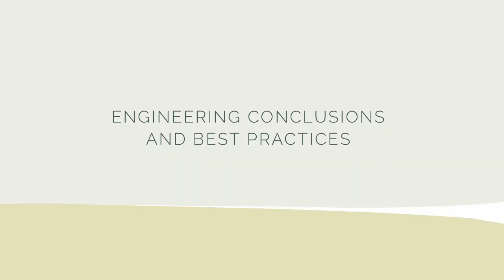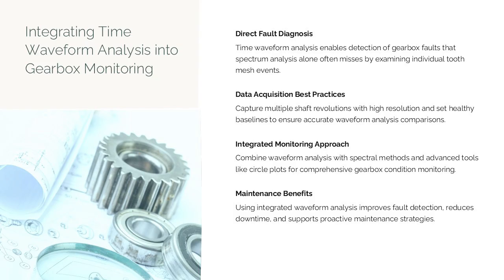Integrating time waveform analysis into gearbox monitoring, engineering conclusions and best practices. Time waveform analysis provides a direct and physically intuitive method for diagnosing gearbox faults that cannot be reliably detected using spectrum analysis alone. By observing individual tooth mesh events, engineers can identify localized defects, determine fault severity, and make informed maintenance decisions with greater confidence.